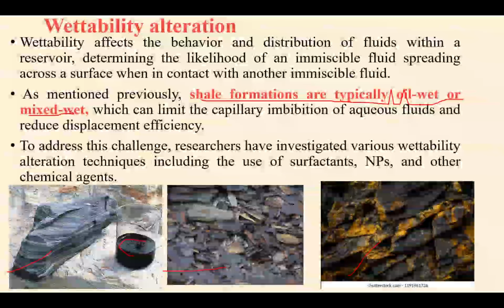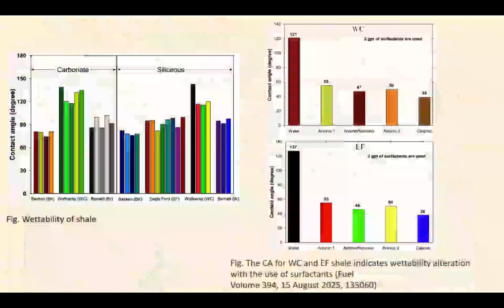And this clay component interacts with the asphaltenic or resinic components of the crude oil, and they are tightly adsorbed or attracted, and this occurs over millions of years, and subsequently they are converted to oil-wet. And surfactant injection significantly improves the recovery, particularly the displacement efficiency, by lowering the IFT, then altering the wettability, which is the most important parameter here, and emulsification.